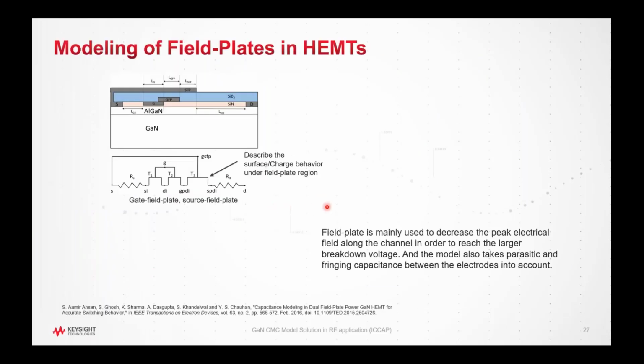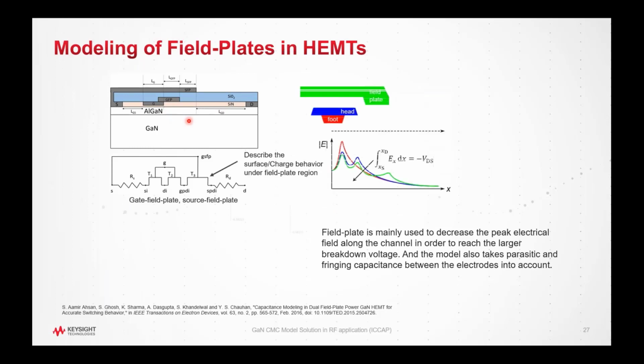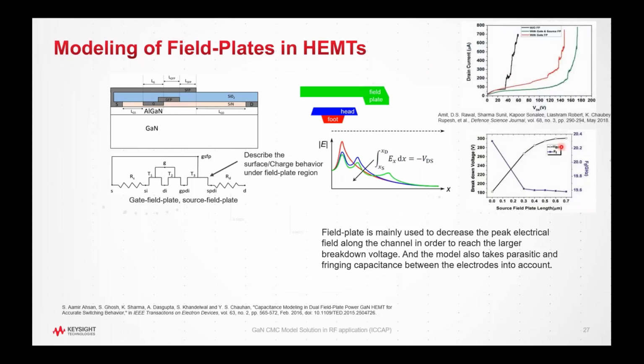And the next one is the field plate. It's not the focus today, like I said, but this is also included in these two models. If you're using power devices, then you have the field plate, and the purpose of having the field plate is just to extend the breakdown voltage, or make the breakdown voltage larger. The more field plate you have, the more you will minimize the peak of the electric field in the channel, and so on. There are several research works on how the field plates affect the breakdown voltage.